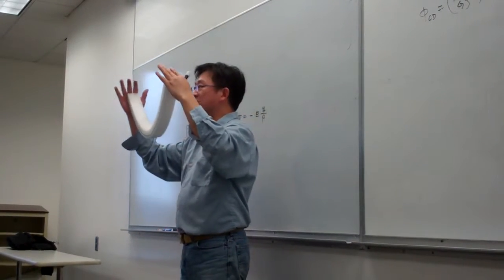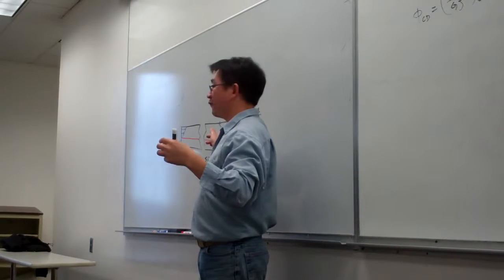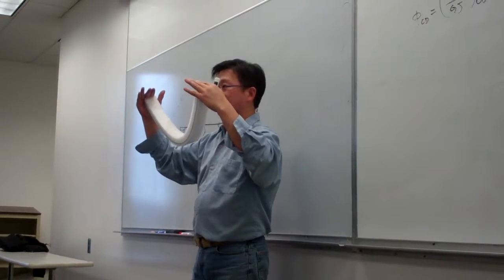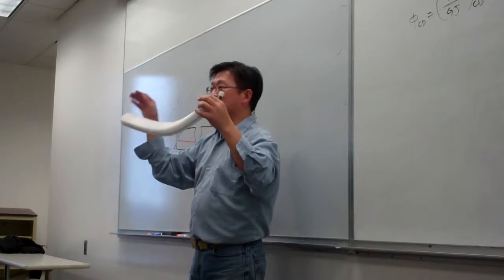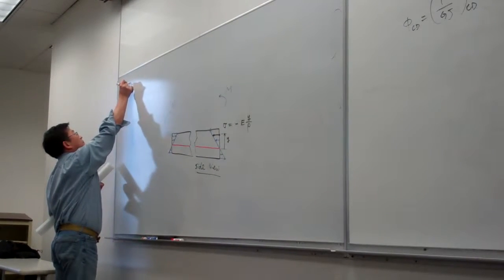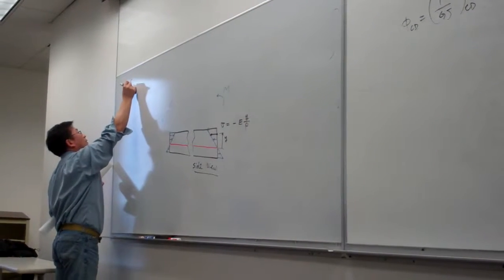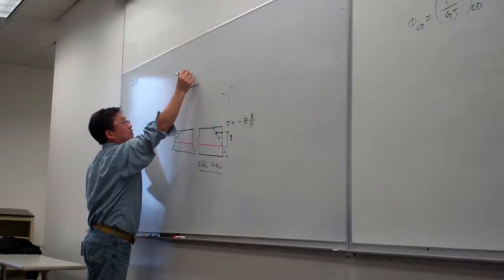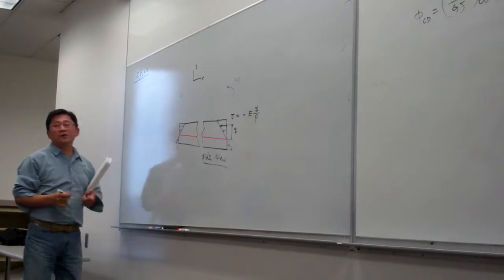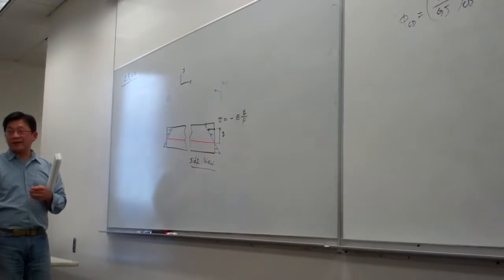So the externally applied bending induces a certain internal reaction, and that reaction causes such deformation. In terms of force equilibrium, the externally applied loading, which is bending, must be in balance with all the internal reactions. So let me define this as the XY coordinate system, with the X-axis horizontal. First, we take the equilibrium equation in the axial, horizontal direction equal to 0, and see what happens.